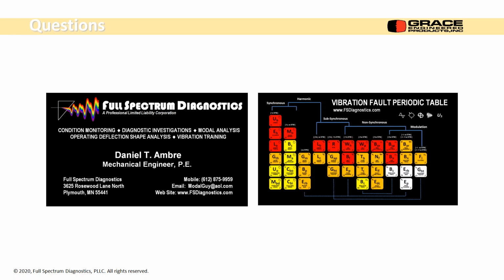But again, you're taking measurements. Your first day or two of measurements could be every 5 minutes or every 20 minutes, and you could get a couple thousand measurements and really understand where the actual overall alarm is. So instead of 0.325, it might be 0.298, something like that. That doesn't sound like a big deal, but it is.